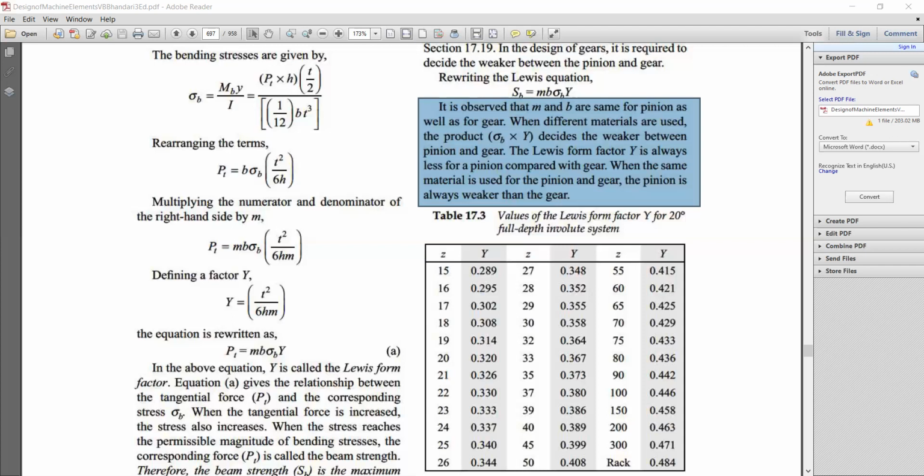This form factor we consider in helical gear design and bevel gear design. Mt is the torque transmitted by pinion, and E is the equivalent Young's modulus. Okay, let's see how it is mentioned. First, page number 8.2 gives the idea about the basic load factors: what are the different factors which need to be considered and how we can calculate them. Load concentration factor we can find out from table number 14. Similarly we can find out the others.